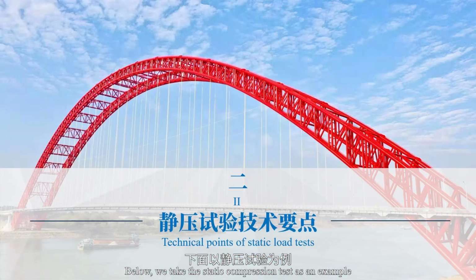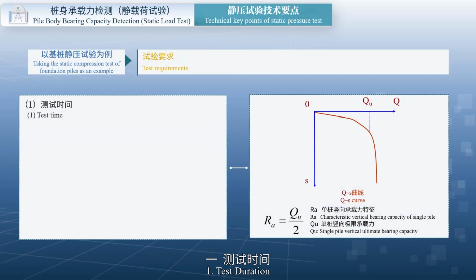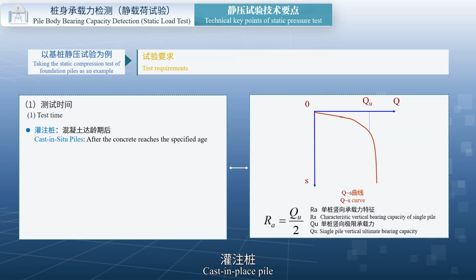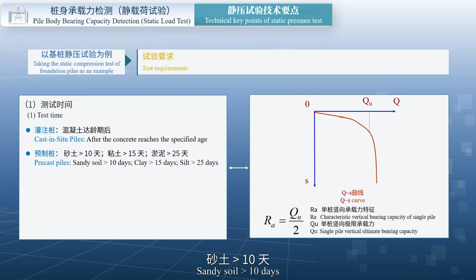Below, we take the static compression test as an example. Briefly introduce the relevant technical requirements. Test requirements. First, test duration. Cast in place pile, after concrete reaches required age. Precast pile: sandy soil is greater than 10 days, clay is greater than 15 days, silt is greater than 25 days.